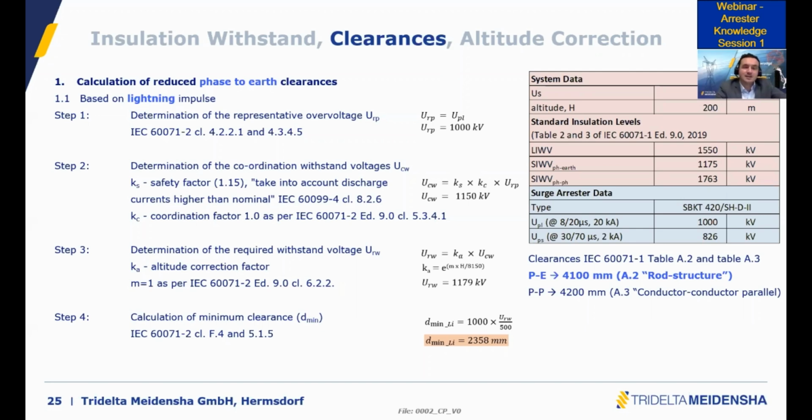Such a BIL means that you have a system voltage of 550 kV. A typical lightning impulse protection level at 20 kA nominal discharge current is not 1,525 kV. Even if you use very cheap varistors, of very low quality, you will never get this value. This is extremely high. A typical value with standard MOV blocks would be 1,000. So I hope this answers the question.